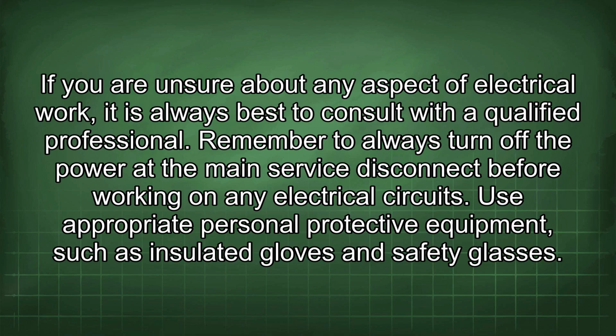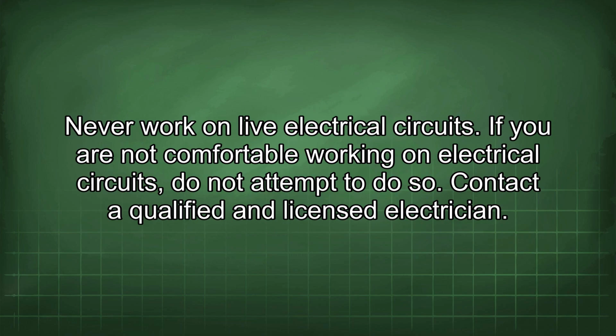Remember to always turn off the power at the main service disconnect before working on any electrical circuits. Use appropriate personal protective equipment, such as insulated gloves and safety glasses. Never work on live electrical circuits. If you are not comfortable working on electrical circuits, do not attempt to do so. Contact a qualified and licensed electrician.